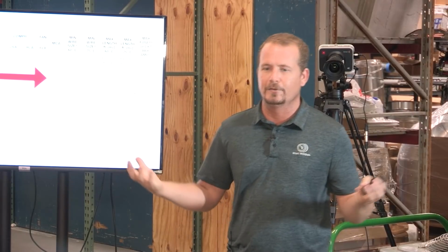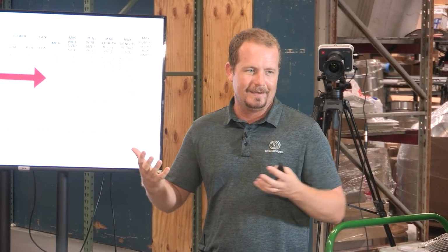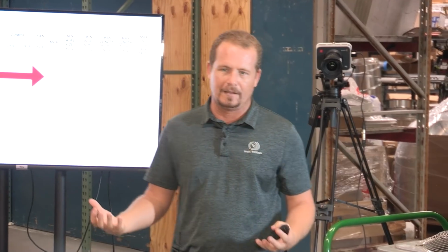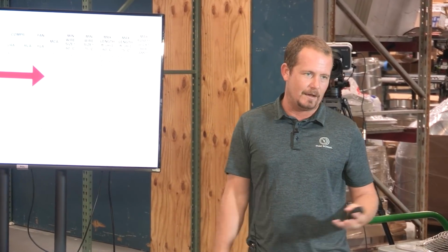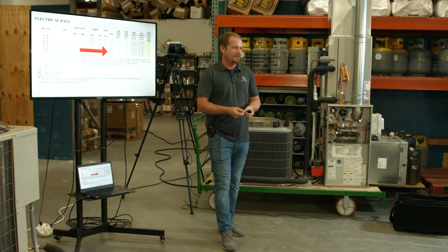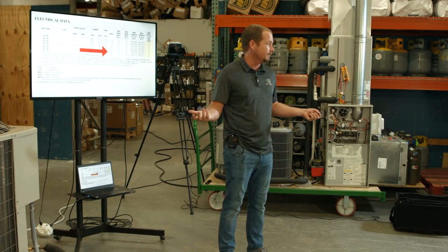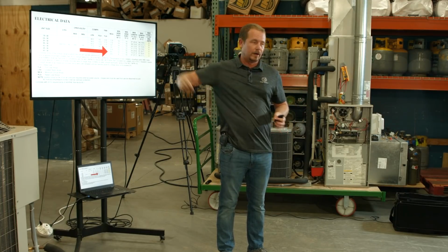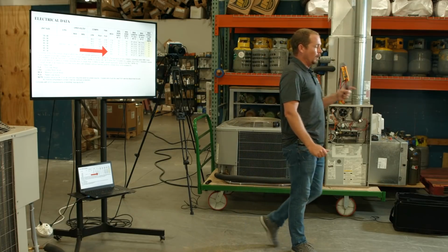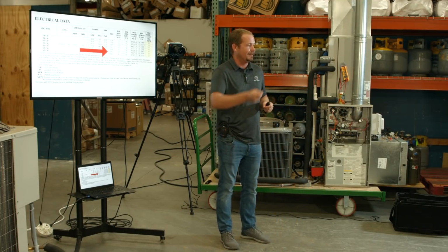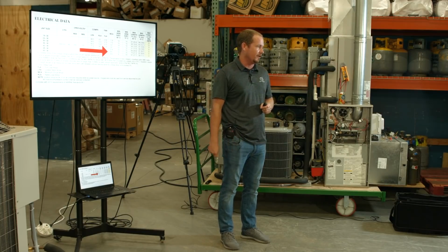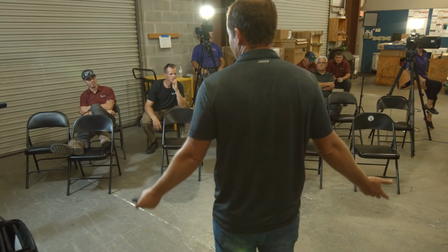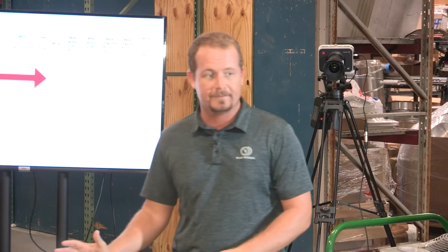First off, you don't have to add up all of the breaker sizes and then size your breaker or wire off of that. That's not how that works. Think of convenience outlets as an example. You'll have multiple outlets in your house connected to a 15 amp breaker or a 20 amp breaker. We'll say 15 because a lot of houses are. So imagine you've got a 15 amp breaker with number 14 wire, wired up to all of these outlets. What prevents you from hooking a toaster up to one outlet, a vacuum cleaner to another, and a space heater to a third, and firing them all up? Nothing prevents you from doing it. It's just going to trip, right? So it's safe. Why is it safe?